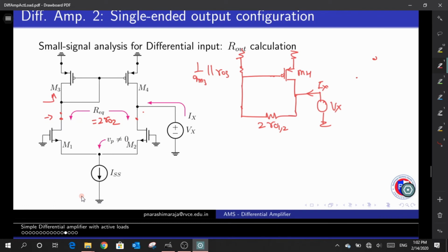Is that clear? Now, one of the currents is through this path, path number 1. Because of this current mirroring structure, the same current would then be reflected here as well, on this particular node. Are you clear? So this current flow would then be reflected here through the value of VGS. So that is my second current.